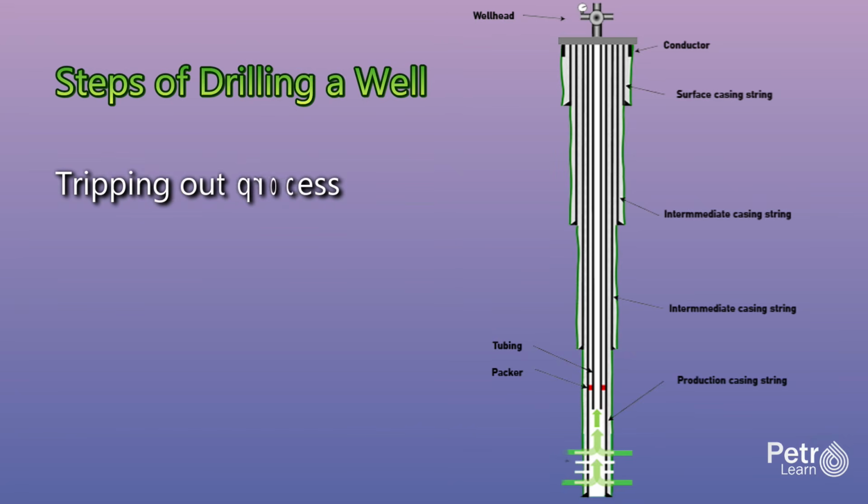The driller raises the traveling block, lifting the drill string. When a tool joint appears above the rig floor, slips are set. The connection is broken with tongs, and the joint is lifted clear and racked vertically. This continues, removing pipe one joint or one stand at a time until the entire drill string is out. This can take several hours for a deep well. The conductor casing is then run into the hole.